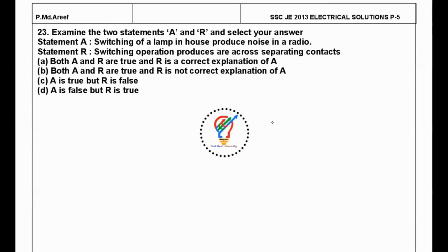Our power system will have both inductors and capacitance. So first of all, when the lamp is conducting, say the lamp here, which is operated with a switch like this, assuming that the lamp is an inductive load and we have capacitance in our transmission lines. So when we open the contacts of the circuit breaker while it's conducting, whatever energy is stored in the inductor, that is half L i square, is stored here. So once you open the circuit or switch, what will happen?